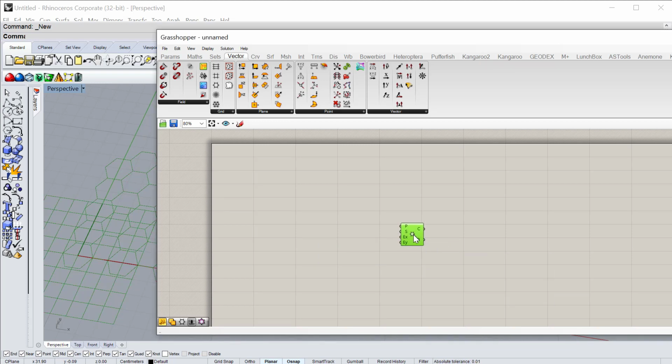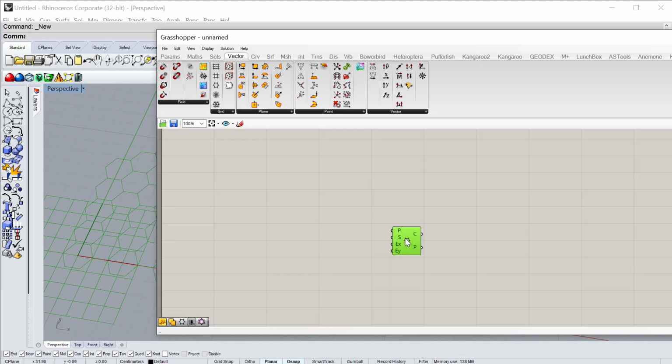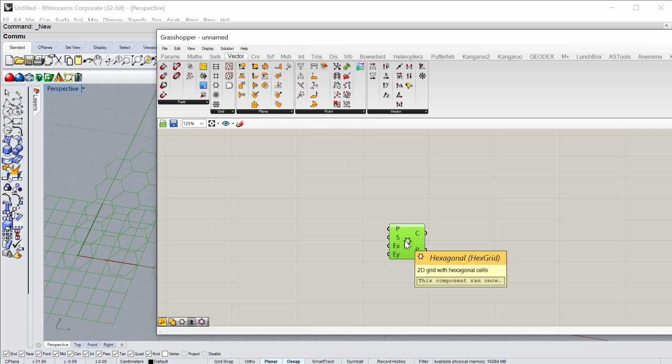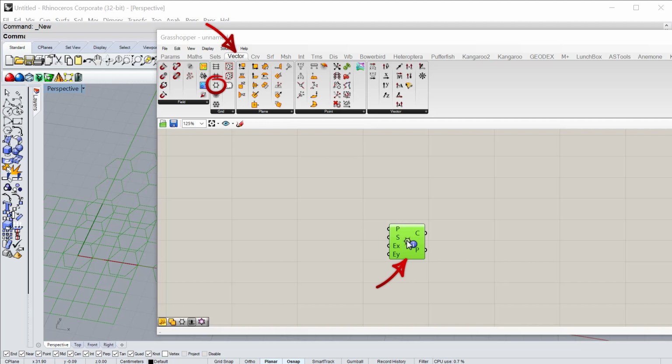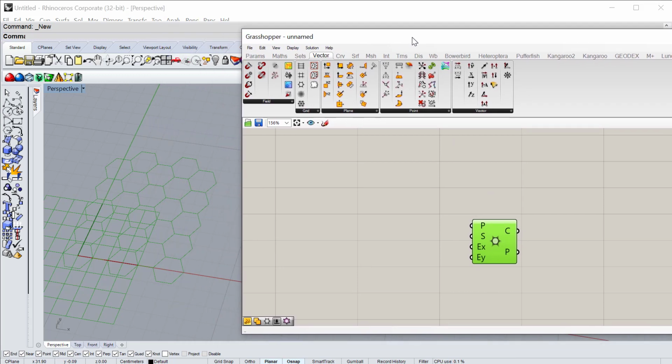And here we go. Here's a Grasshopper node, and let's say you open up somebody else's definition and you want to find out where this node comes from. You can press Control Alt, and it will tell you at the top with these arrows where this node can be found. Now, this is just like any other node structure where there's inputs and outputs, but Grasshopper is really powerful because it works with these lists of data, which can be rearranged in a way that gives you different patterns, and it's really easy to work with and understand.